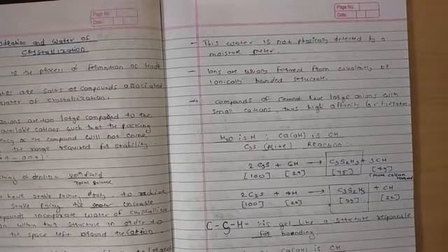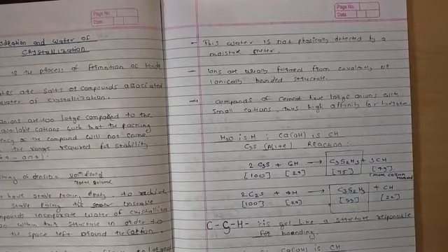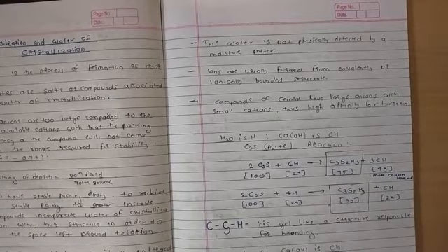In a very detailed manner, we are going to look into hydration some other time, but let us do a quick revision. What exactly is the hydration process? Hydration water is chemically bound in a structure and therefore not available for processes such as fungal growth. It is the water available for the structural elements present in the cement. It is not free water, which after some time could lead to fungal infection in the cement and concrete.